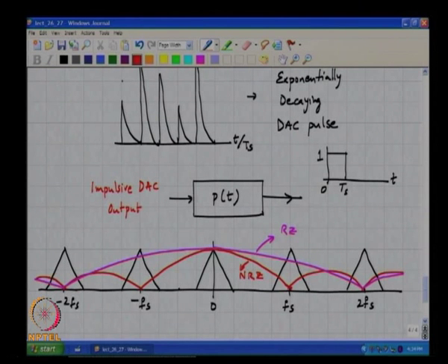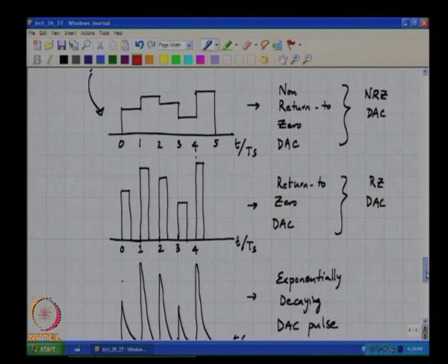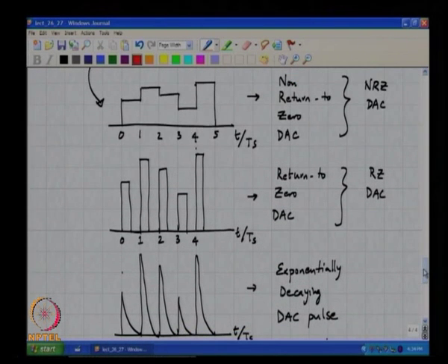I mean see the amount of high frequency energy is proportional to the number of jumps you have in the waveform, or the magnitude of the jumps, correct. So, you can see that clearly in every clock sample there is a guaranteed jump, 2 jumps of equal and opposite magnitude.